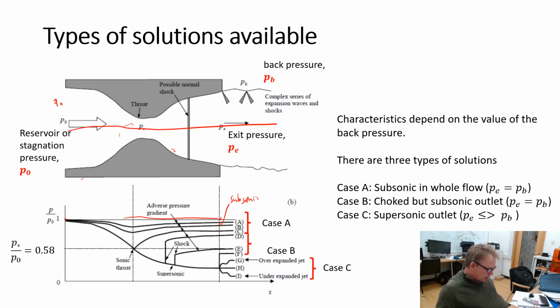Subsonic. And this will drive a subsonic flow. We met before that, and we know from intuition, that when we drive a flow through this constriction, the flow will get faster as it goes through the throat. By Bernoulli's equation, it gets faster, the pressure drops, and so we'll see a reduction in the pressure at the throat. We see here, this is coming down and then coming back up.